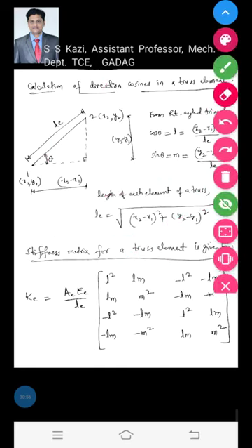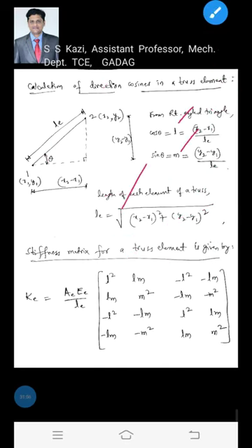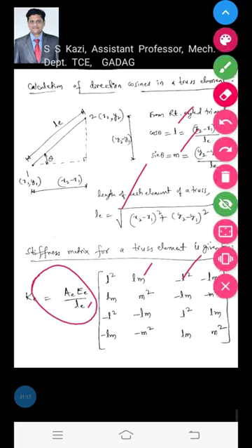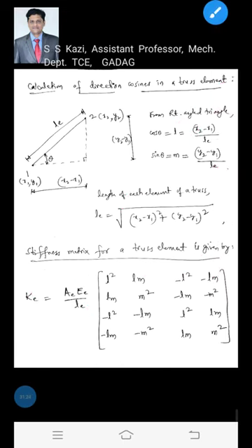Once you find the L, M and LE, then you just substitute here and get the stiffness matrix for all the elements of a truss and assemble those matrices to get the global matrix and global equilibrium equation. Apply the elimination approach to determine the unknown nodal displacements, stresses in each element and support reactions, as I am going to discuss in the next video of this truss problems.